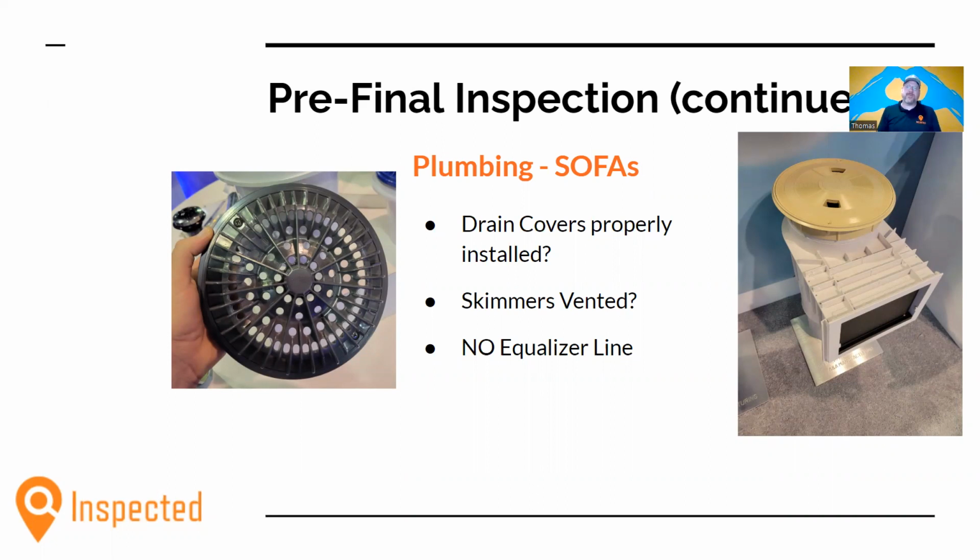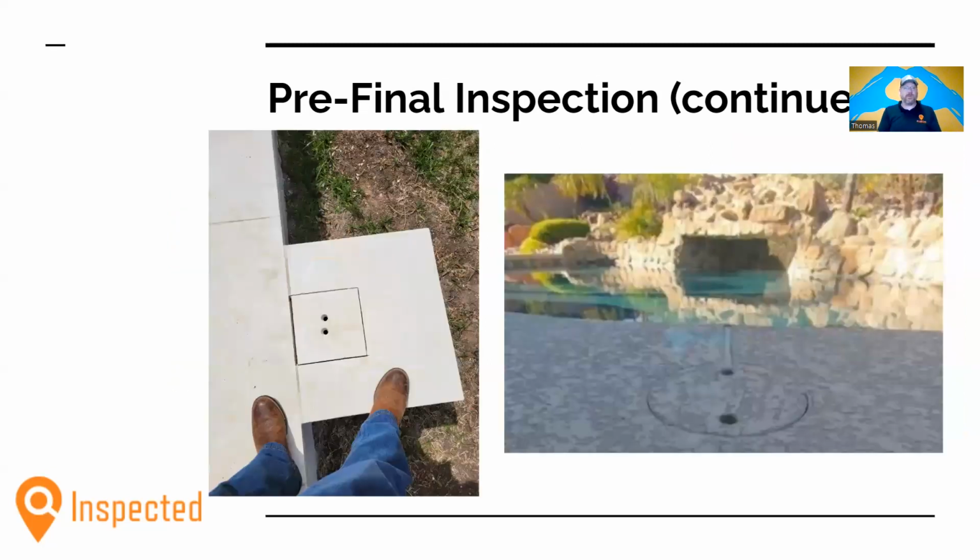It's also so that you can prevent the skimmer, if there's too much rain or somebody leaves the hose in the pool or you have a malfunctioning autofill, from making the water level rise above the skimmer throat and create a submerged suction and entrapment danger. The holes in the top of that lid break that vacuum. And you are welcome to install aftermarket skimmer lids as long as they have a means by which to vent to the atmosphere and prevent a vacuum.